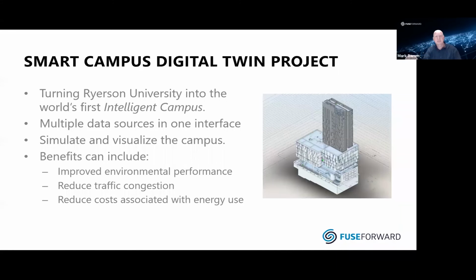So instead of creating fixed set points on a thermostat, where you'd say, I want it at 78 degrees Fahrenheit or 22 degrees or 20 degrees Celsius in the morning, and I want to change it in the afternoons, I can start creating dynamic set points to change it based upon the density of people within a room. Using dynamic set pointing and algorithms that we can then verify inside the digital twin, we're able to save upwards of 20 to 30% energy use within the building.